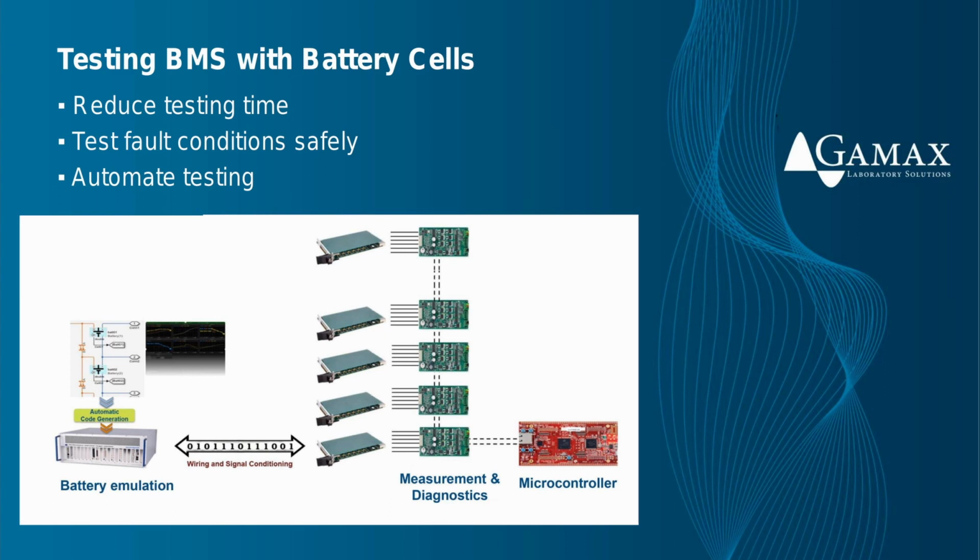This is the model you may have used for testing BMS algorithms in desktop simulation. Next, we generate C code from the battery model and compile into a real-time application, which gets deployed and executed in real time by a dedicated real-time target computer. This target computer must have required peripherals to convert numerical values into physical signals, such as cell voltages or temperature.